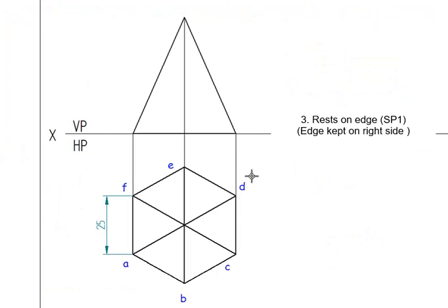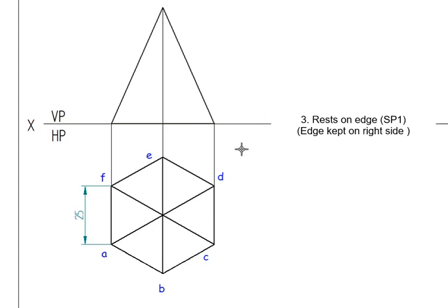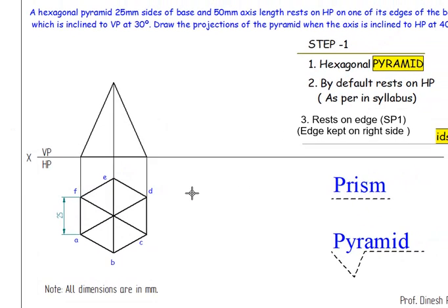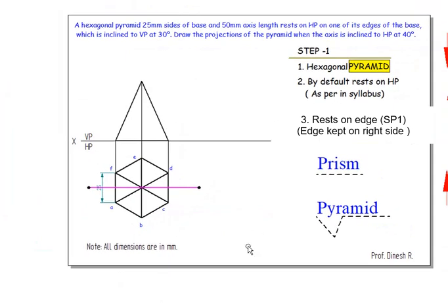So just join this. Now I need to see the outer boundary, whatever I have drawn is going to be thick lines. So next thing is I am going to draw an imaginary horizontal line. This is just for your reference. So below this point, which is nothing but the apex point, this is going to be the first nearest point, second nearest point is A and C. So line joining A, B should be in thick lines.